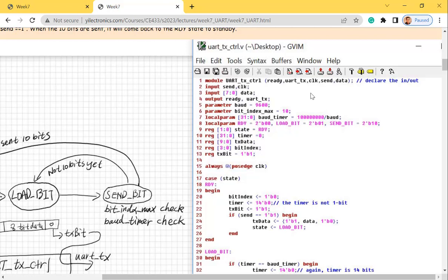You push it. Right now you want to design something which can respond to the push and then convert it into something and then send it to the data line, so the TX can do the job. So what do you still need to implement this kind of verification idea here? Module for the button. Do you need the module for the button? Well, what is a button? Button C, for example, BTNC. That's a physical pin. It's in the constraint file, so you can directly use it. All right?